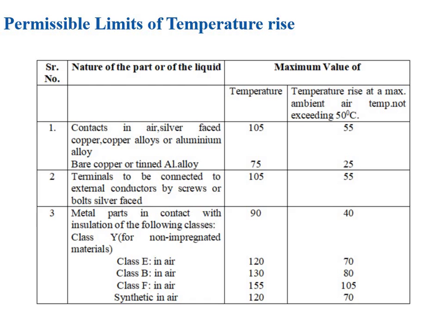Then the values of temperature and temperature rise are valid whether or not the conductor connected to the terminals is silver faced, and the temperature shall not reach a value where the elasticity of the material is impaired. So for pure copper, this implies a temperature limit of say 75 degrees centigrade.